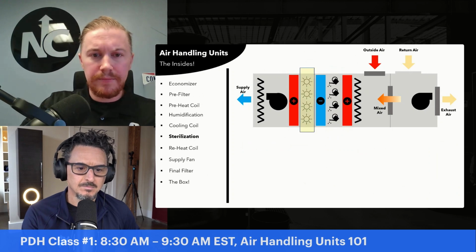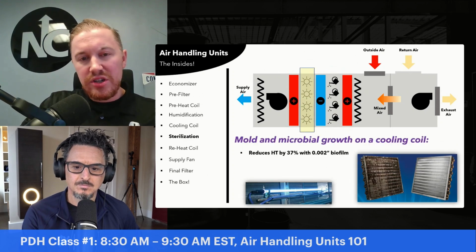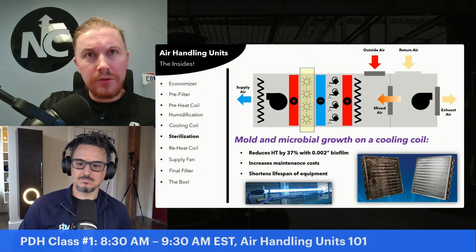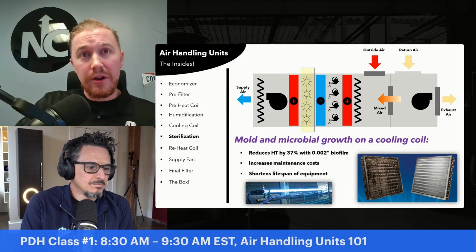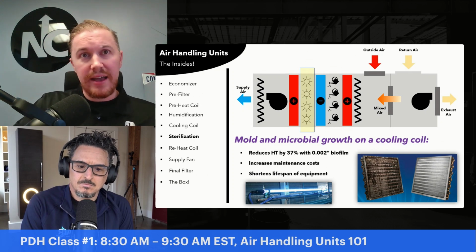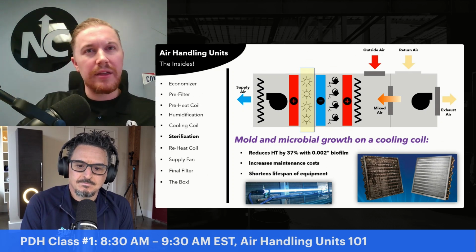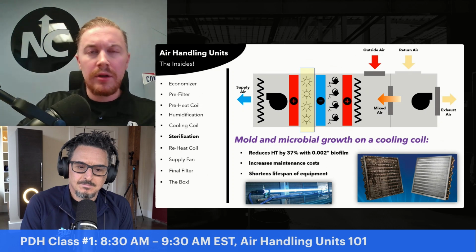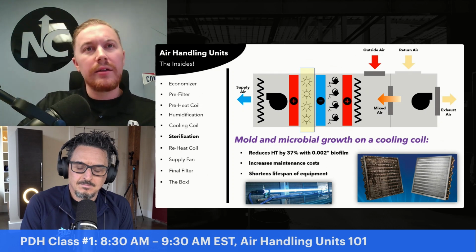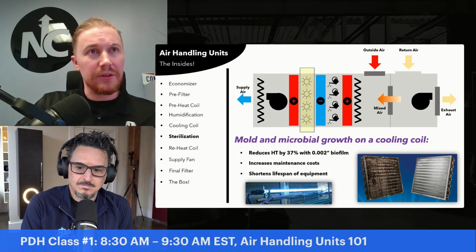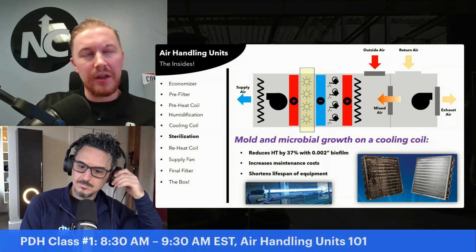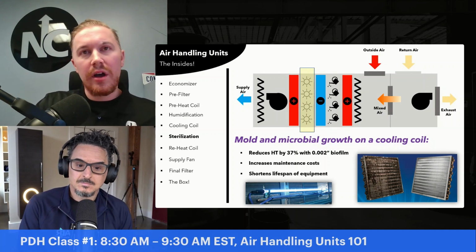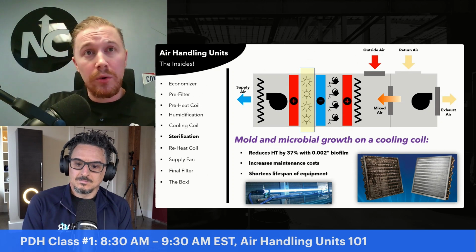Okay. We might see UV sterilization on the face of the cooling coil to avoid mold and mildew growth. We might even see it in the airstream to decontaminate as we pass the air through the air handling unit. One big thing about UV sterilization, no matter who you go with, you're reducing maintenance requirements with cleaning coils, and you're actually maintaining a better amount of heat transfer. We can see here just with a 0.02 of an inch of biofilm buildup on a cooling coil, we reduce